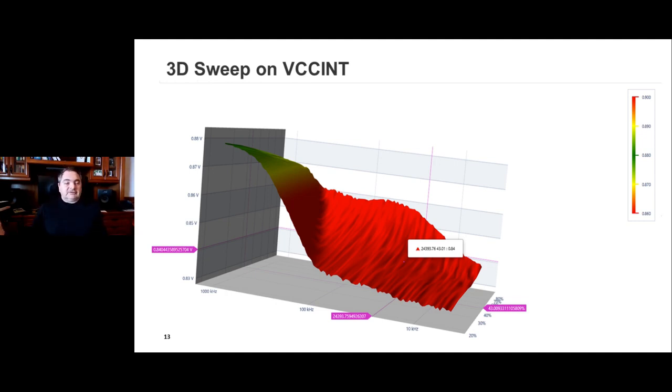We basically have a voltage controlled current sink, which is what our LoadSlammer is, in the FFED or in the passive solution. And that voltage controlled current sink can vary the rise and fall time. It can vary the destination current, and it can vary the duty cycle and the frequency of the pulse as well. So that's a lot of permutations.